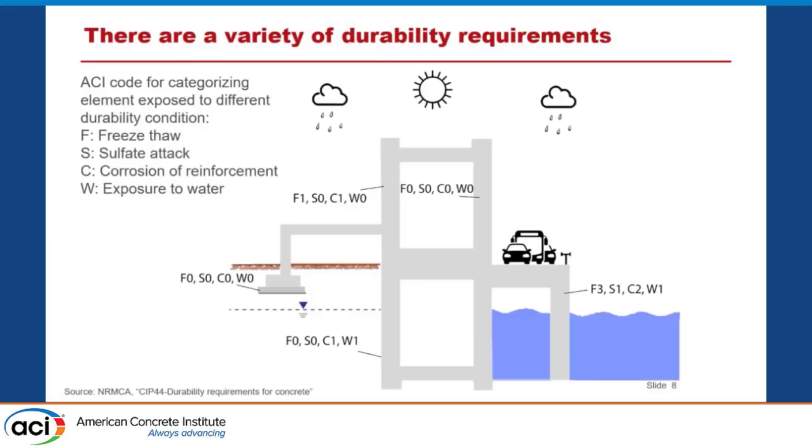This would require us to think about one concrete mix design that satisfies the mechanical performance requirements, but requires much different durability criteria in terms of freeze-thaw resistance, sulfate attack, corrosion of reinforcement, exposure to water, all these important elements that are well addressed in the ACI 318 codes.